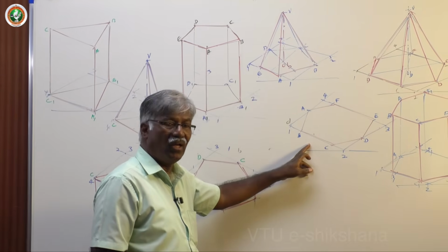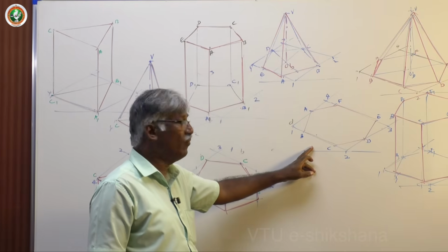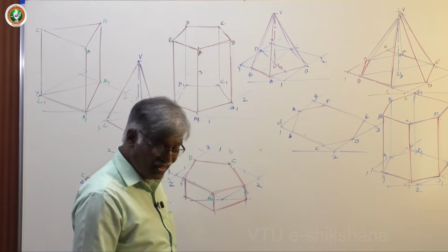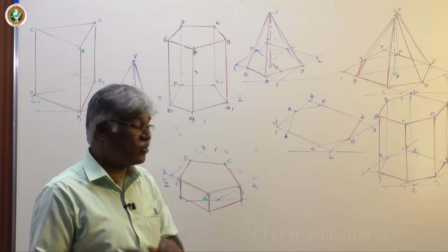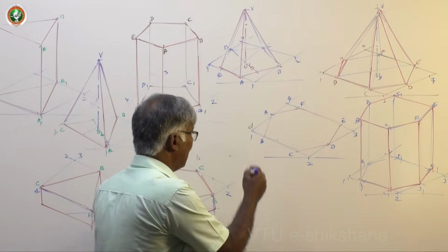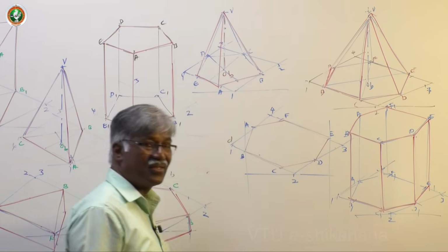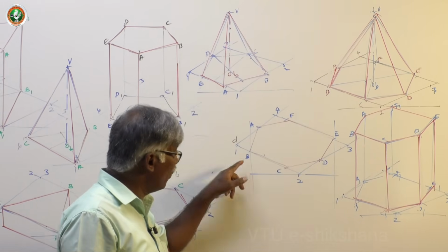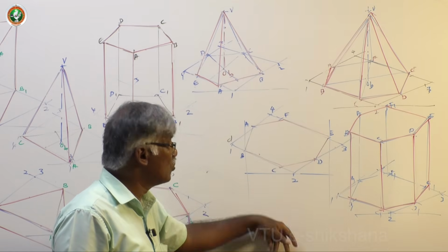Now I will take the isometric projection drawing of a hexagonal block. Again, through which corners do you have to draw vertical lines? As I told you earlier, you draw two extreme vertical lines, including the corners on these two lines and those towards you.